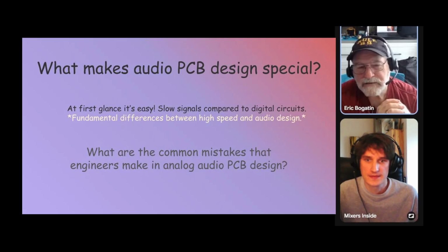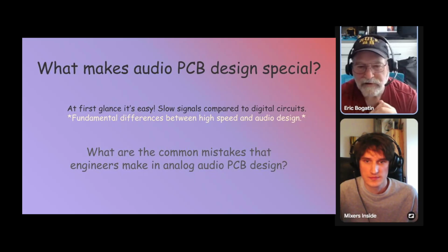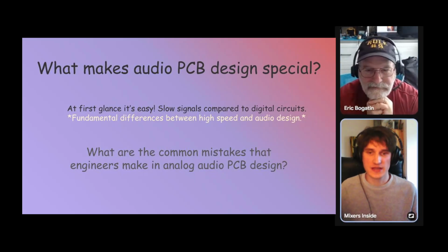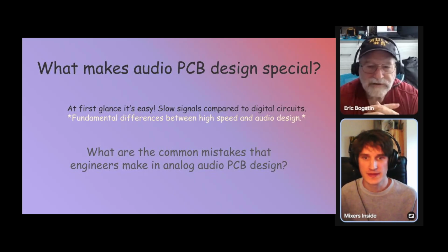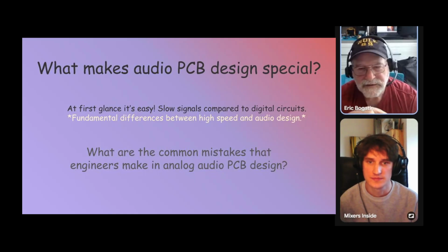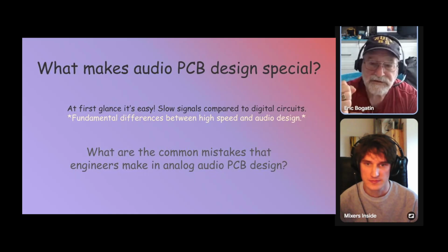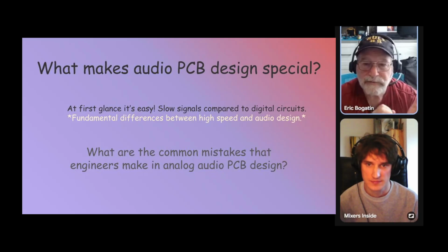And a lot of times that means filtering from the board level to the amplifier level is really important. You mean like power supply filtering, yeah? Power supply filtering, right. 60 hertz is part of it, but with linear supplies or switch mode supplies, it's not so much 60 hertz anymore, but it's the switching frequencies of the switch mode supplies, and it is noise from digital devices that are injecting or causing noise on the power rails.